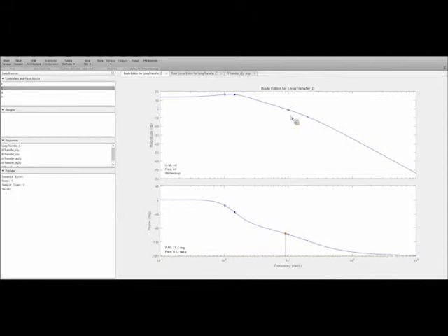And so for this pole and zero, there is essentially no effect. You can almost draw a straight line from the left of this pole and zero to the right of it, right? So you can clearly see how they cancel out. We'll go into this in more detail in the coming lectures, but root locus plots I think are really good for systems of about 4 poles and less. Once you get beyond that, it gets pretty confusing to read what's going on, in my opinion.